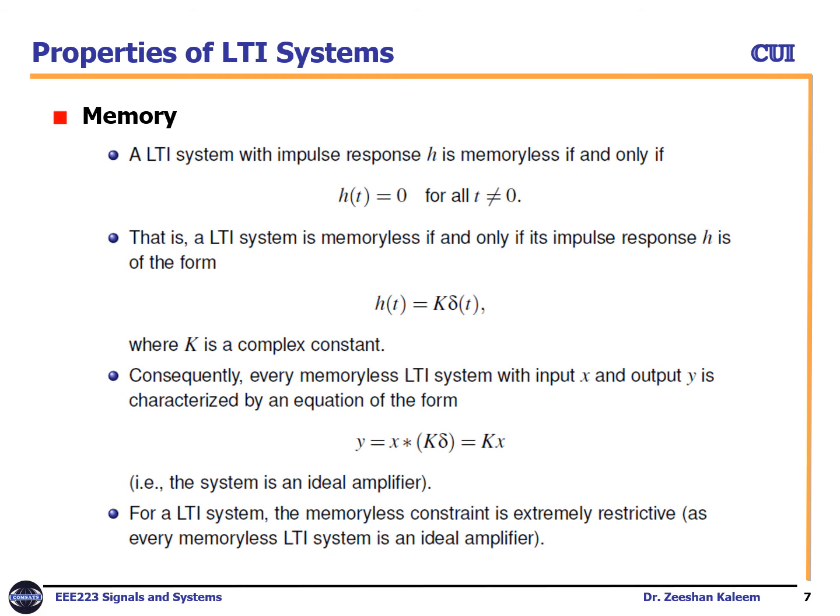Let's discuss another property, memory. An LTI system with impulse response h is memoryless if and only if h(t) equals 0 for all t not equal to 0. As you know, impulse response means that we input the impulse to the system, then the output of the system is called the impulse response.